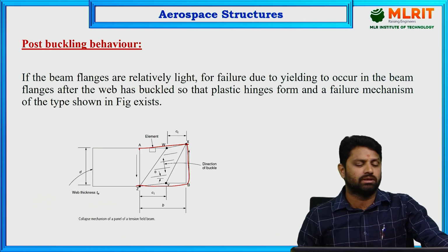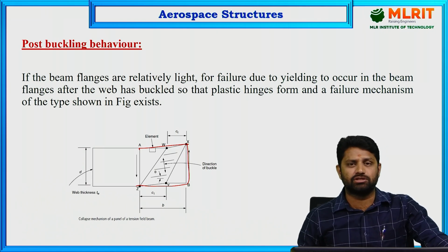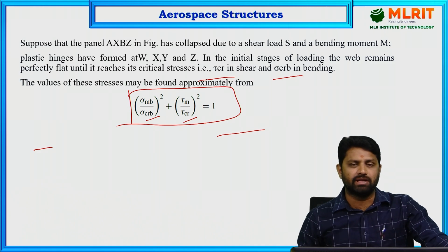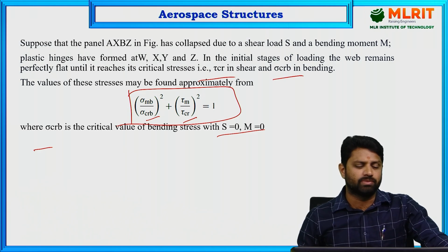So the practical analysis of post buckling behavior can be done using software such as ANSYS or any other software in which you can clearly calculate the values of the stresses after buckling. That is very, very important: after buckling, how much load can be withstood before failure occurs in the material. That is post buckling behavior.